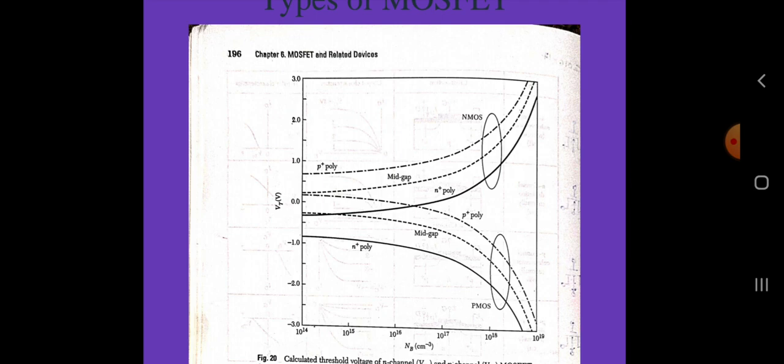Precise control of the threshold voltage of MOSFETs in an integrated circuit is essential for reliable circuit operation. Typically, the threshold voltage is adjusted through an ion implantation into the channel region. For example, a boron implantation through a surface oxide is often used to adjust the threshold voltage of an N-channel MOSFET with a P-type substrate.